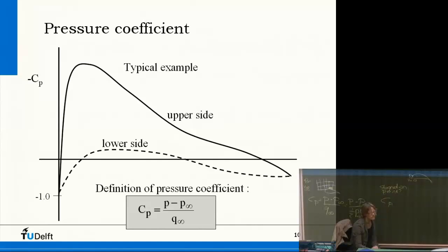But the pressure is not 0 in a stagnation point. No, but this is at infinite conditions. This is not at a location. This is the free stream speed. So the V and the rho are the conditions way up here: 100 meters per second, 1.225 kilograms per meter cubed. So the only thing that's at the location is this one. These are free stream conditions.